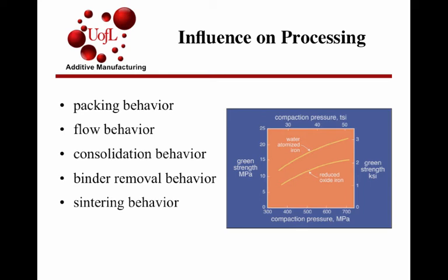Finally, the melting and sintering behavior are going to change based on the packing density, the particle sizes, number of nearest neighbors, and so on. And when all those aspects of creating the shape get affected, the final properties can be affected as well, starting with density and then from there on going into other aspects, including grain size, phase structure, so on. In addition, the ability to hold dimensions is going to change as well. So that indicates why it's important to understand powder attributes and their influence on outcomes during 3D printing.